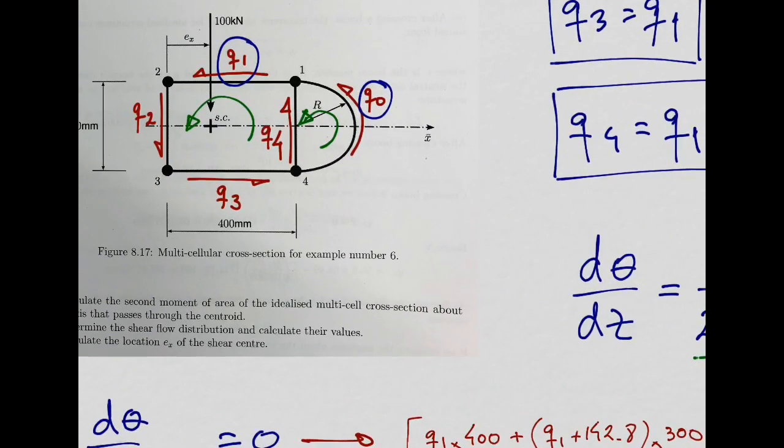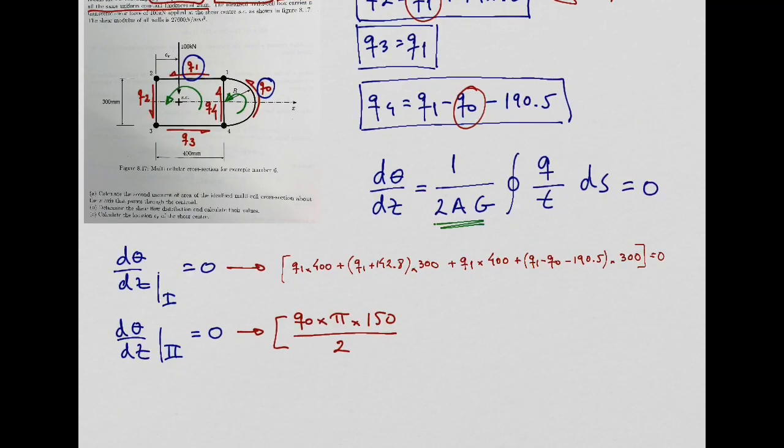Now, this shear flow Q4 is going to be opposite with the anti-clockwise rotation of the cell. You agree with me? So we need to use a negative, this minus now, okay? You understand? So we are assuming for the cell that anti-clockwise rotations are going to be positive.